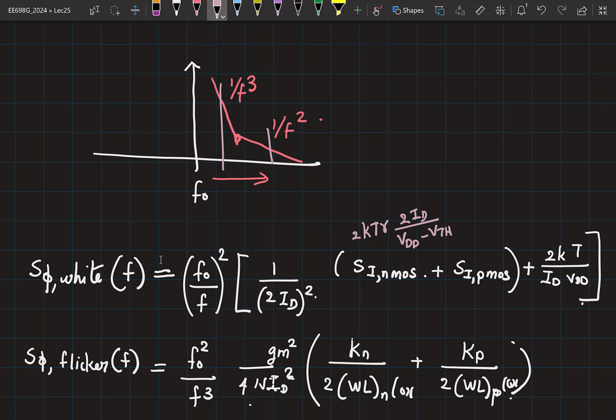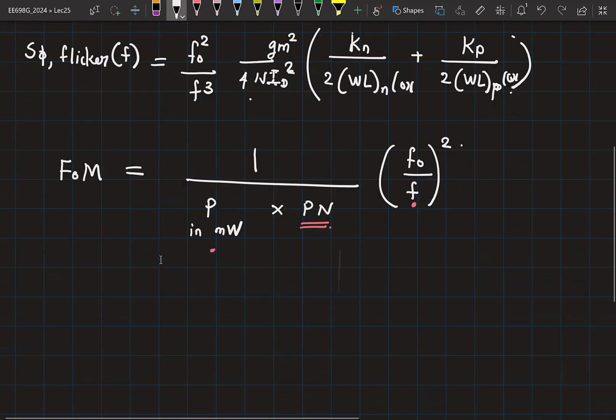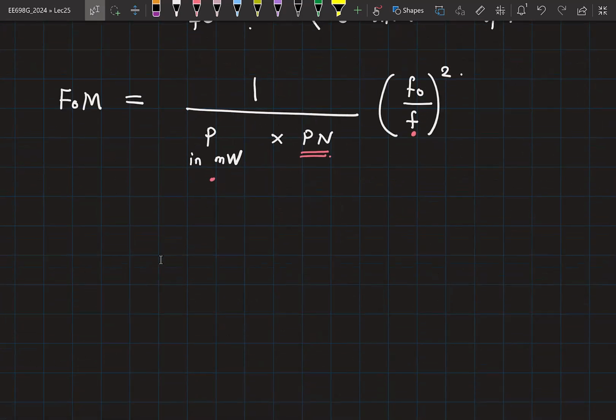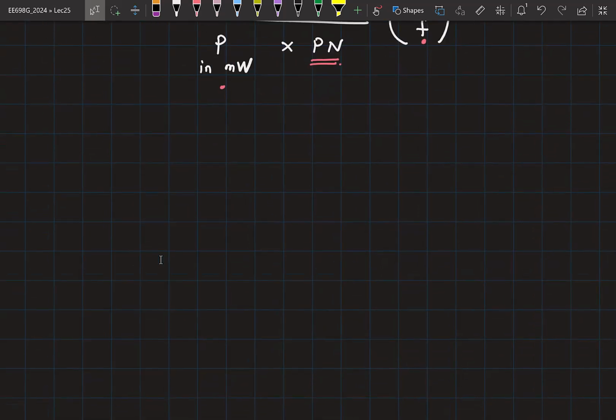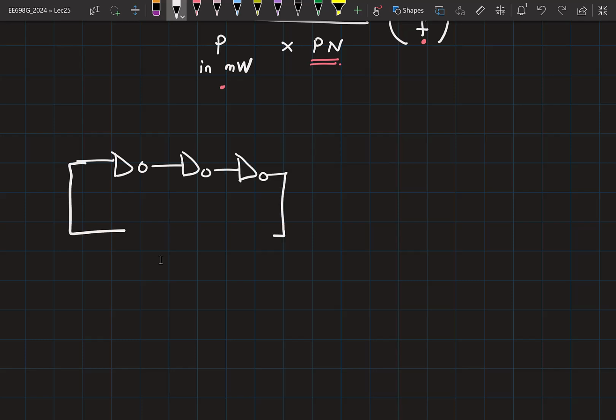Okay. So now we get back to our attempt at designing a very good ring oscillator with as few steps as possible. We designed a ring with 3 stages. We started out with a reference design with minimal sizes and a minimal number of stages, and we found that it had a very large oscillation frequency.